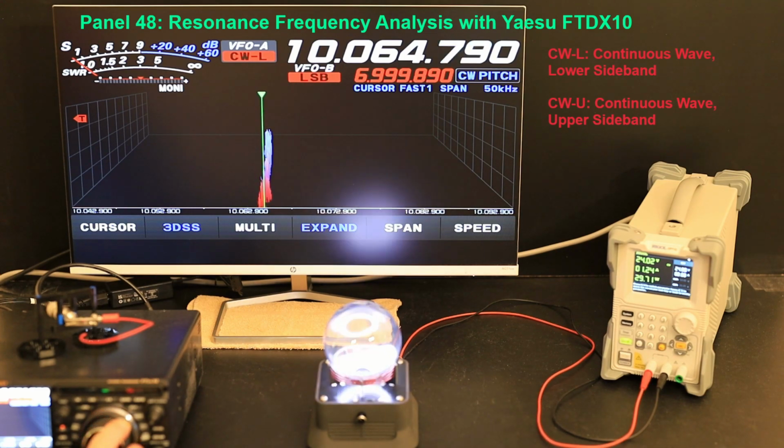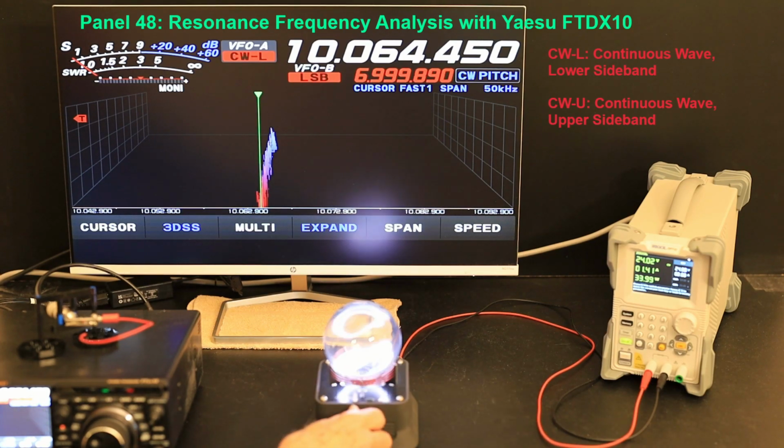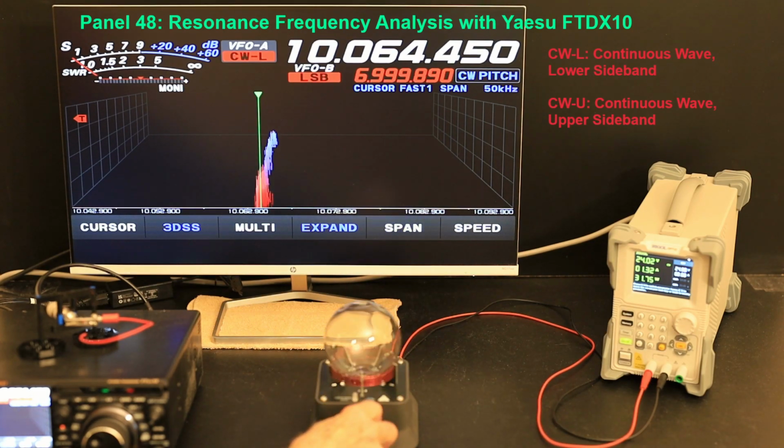is off. For high-frequency RF radiation near 10 MHz, CW modes like CWL and CWU are most effective. These modes toggle the carrier to produce RF energy bursts, enabling precise narrowband frequency identification. In CWL and CWU modes, the carrier frequency is offset by the chosen tone, lowered in CWL and raised in CWU.